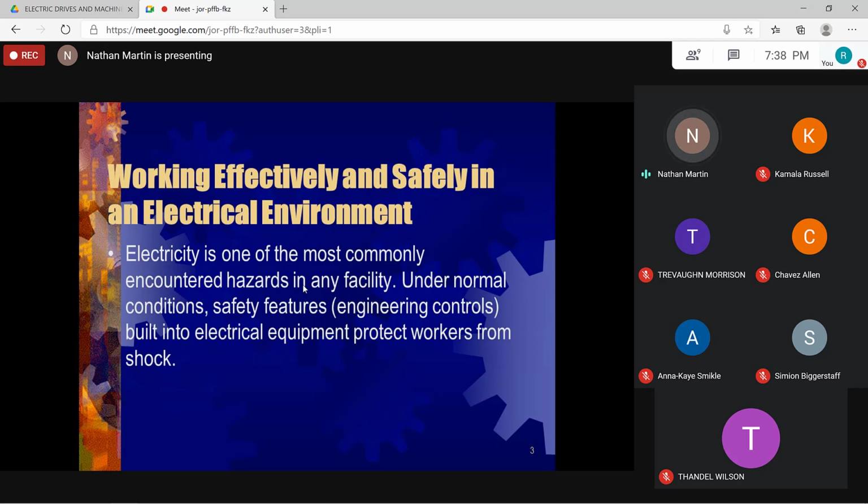The next step now after testing was to pull that neutral, which was connected using a one-bolt clamp, what we call a one-bolt clamp in the field, right? Now, that one-bolt clamp for the neutral, and let me tell you this, most of the time when you're having problems like this, 90% of the time it's going to be the neutral, right? The neutral is not taped when you connect the neutral in a system. That's from your twisted pair, the 2 black wires that come to your house and the shiny one. The shiny one without any insulation is the neutral, for persons who are unaware, right?